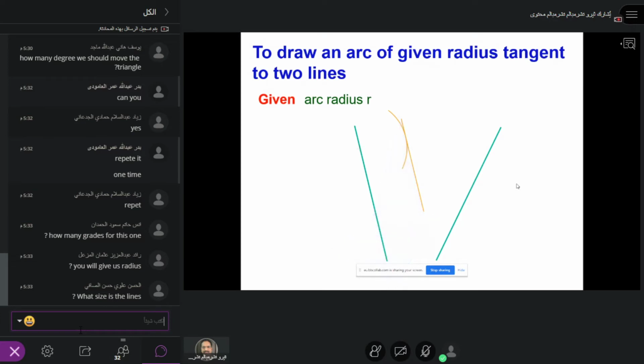Very similarly, from the other line, first make the arc, use the same tri-square as shown, and then slide it by using the 45-45 tri-square, and draw the tangent by moving it all the way to the arc, and joining the line from the radius.